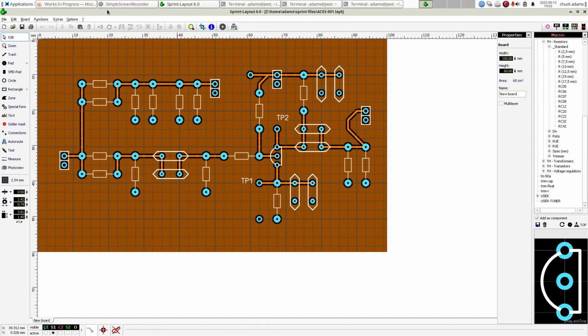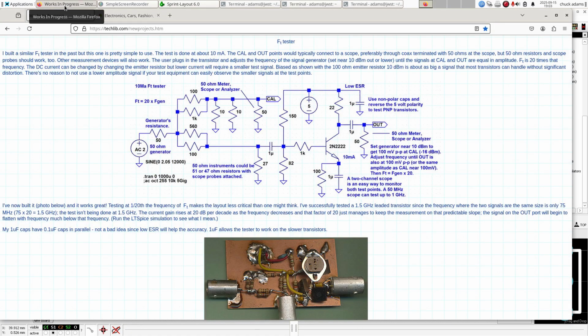Everything's on there. One of the things that I want to experiment with is that I'm going to change the voltages here. So I want to know what the current is, and that's it. I need to measure the voltage here, divide it by 100, and that'll give me the current. I want to measure the voltage across the transistor from collector to emitter. So here, if I want to measure the voltage from the collector to emitter, how would you do it here? Well, it's going to be a little bit difficult.